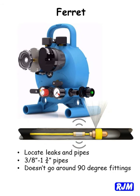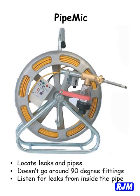The ferret is placed inside the pipe and pumped through the pipe until it reaches the leak. It has an integrated sonde built into it that can be used to locate the pipe and the leak. It only works on pipes without tight bends. The pipe mic inserts into live water lines to listen for water leaks from inside the pipe.